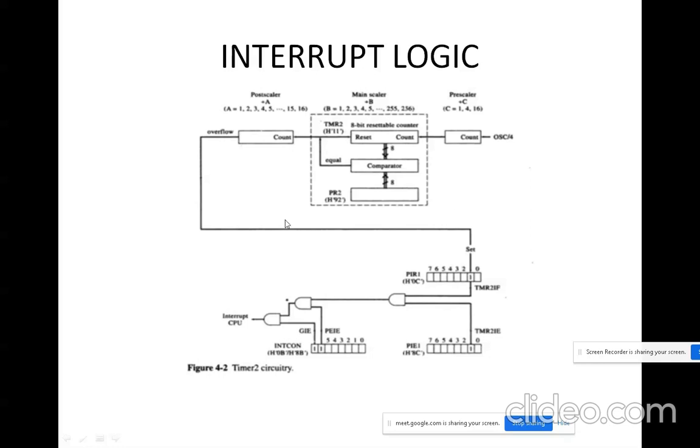The counting of the counter is maintained by the TMR, this is the timer 2 counter. The counter will be set and reset here by using this counter register. Then you will compare the value of counting with the count value set in your program or instruction. After it reaches zero, it will return back to the main program. The diagram is represented here.